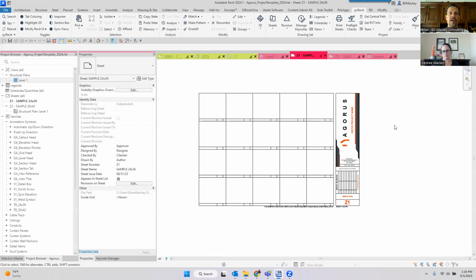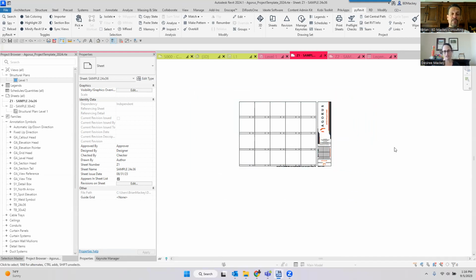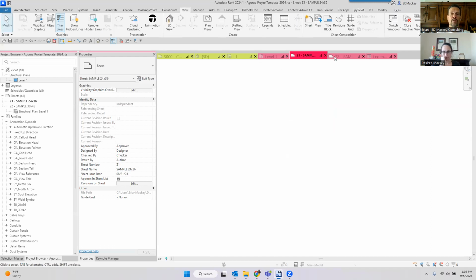And I'm like, why is this not lining up for you? It was hilarious. Came to find out that I think whoever originally created their template deleted the title block family and then came in and was like, oh, so I delete the title block family. And here's like, oh, okay, cool. Most people don't know you can go to the View tab and then you can say place a title block.